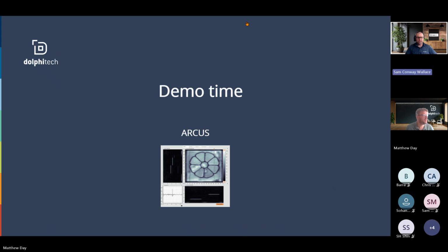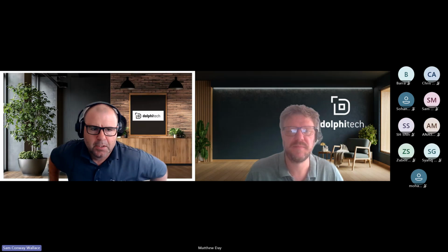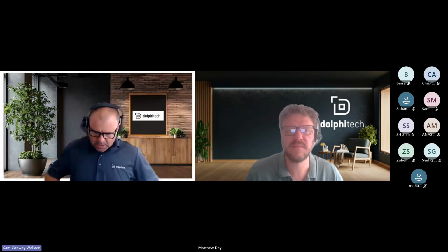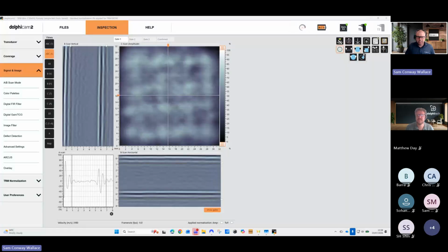Cheers, thank you, Matt. Hello, everybody. Hopefully you can see my screen. What I'm going to demonstrate to you today, I've already set up the basic settings. What I've got in front of me are 2 carbon fiber samples. Hopefully you can see the flat bottom hole in the bottom. We often use flat bottom holes because they are very good at representing the delaminations that we commonly come across in our carbon fiber panels.